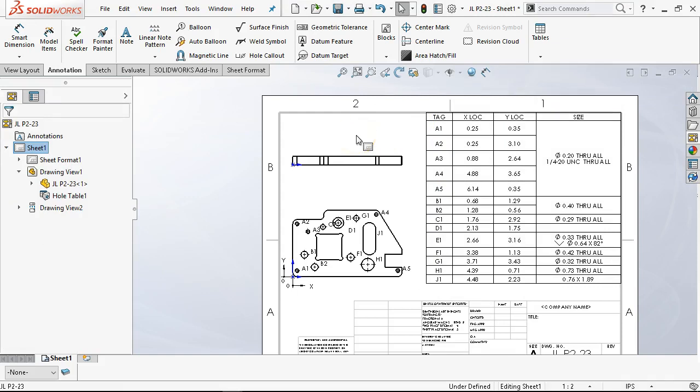All right, that gives enough information to get started, yes? And that magic only happens if you've generated the holes using Hole Wizard, right? For the most part, yeah. Because the slot and the through hole were not generated by Hole Wizard, they'll still be included. If you want it to recognize the drill diameter and the tap, that would have to be a Hole Wizard item. The countersink, hole wizard item. If it's just a set of through holes, if I had left this alone and everything was in one sketch, I believe it would still recognize the holes as the geometry and divvy them up on size, but you would not have the additional tap or the countersink or whatever geometry we're looking to put on there.